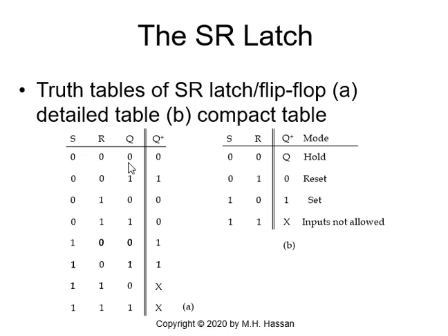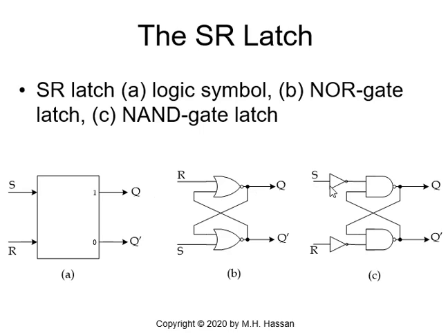When we apply S and R 0, 0, we are applying 1, 1 to the NAND gates because those are inverted.